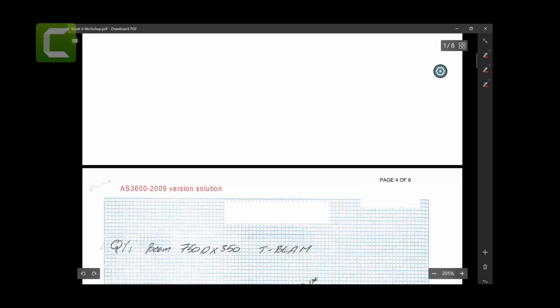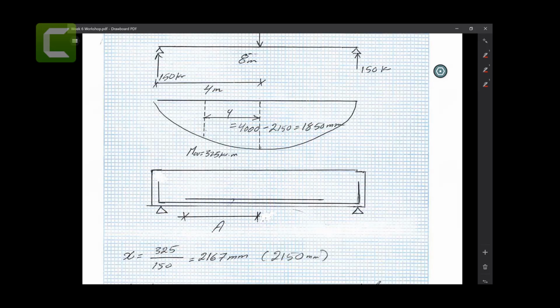So what happens here? The standards want to recognize that okay, you have this 650 kilonewton meters maximum moment, but look, the moment here is not that big, so you don't need to provide the reinforcement that you are providing here. You can cut it off, because in this region your bending moment is small, so you don't require that much reinforcement. So standards allow you to make the curtailments, meaning it doesn't need to extend, you can cut it off. So this example wants to tell us where you are going to cut off.